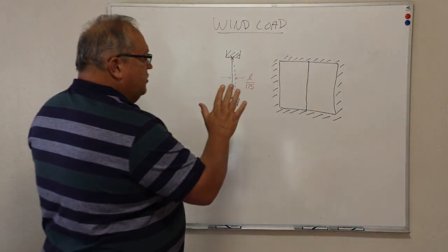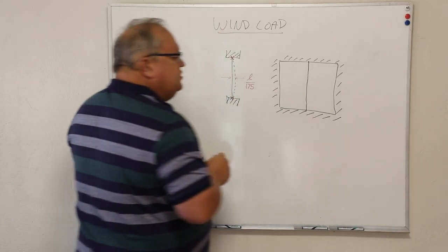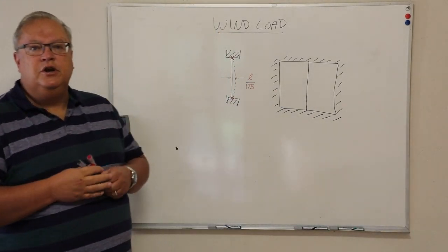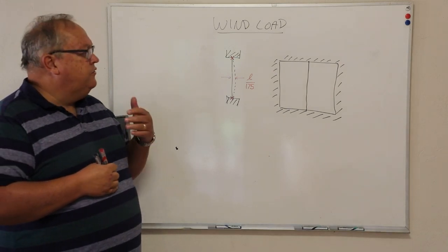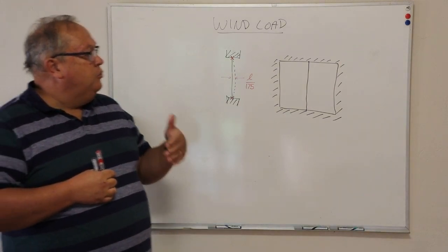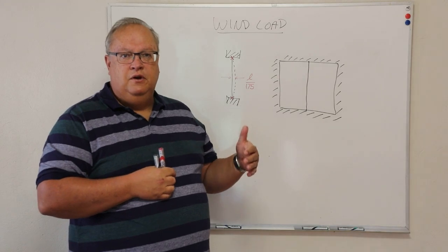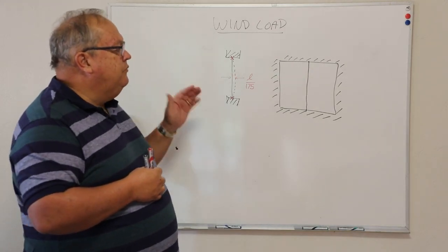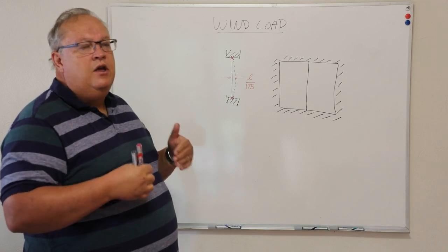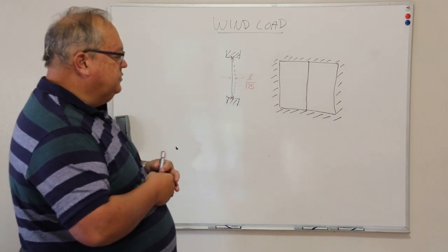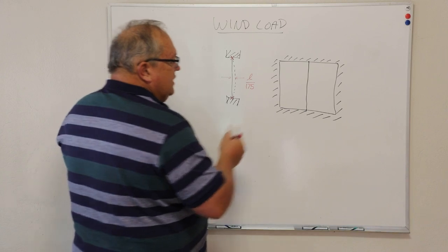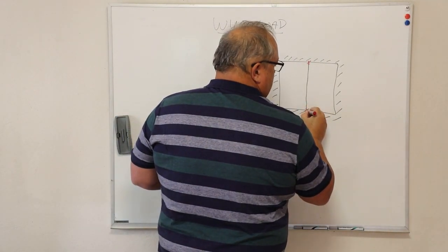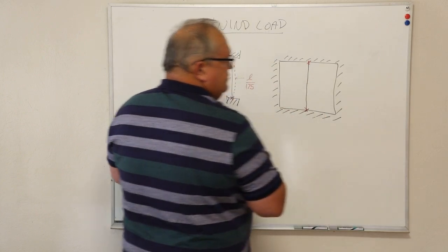So I'm not concerned about the frame, and in fact you don't need to build any structural strength into your framing in general. As long as you adhere to the regulations of how and where to attach your frame to the brickwork or the surrounding structure, your aluminium frame does not have to carry any structural load of this window. It is only this element here, which is fixed at those 2 points, that is subject to movement.